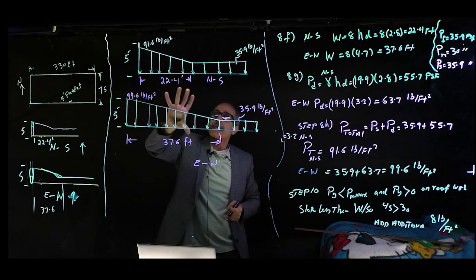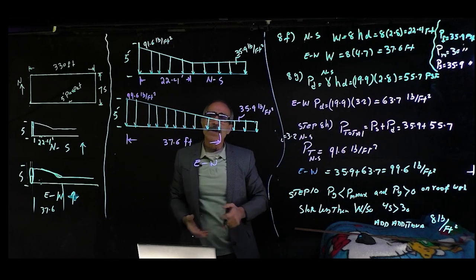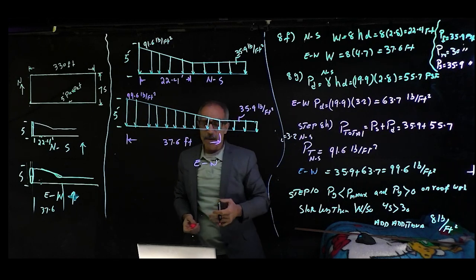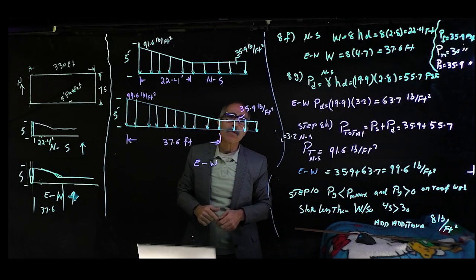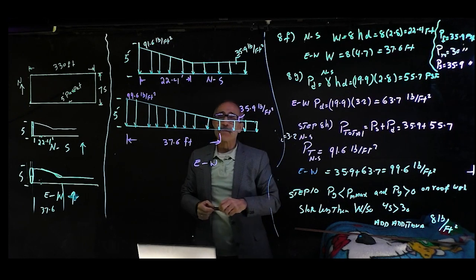This is pound per square foot. So when you do your load calculation, you might have to multiply by the tributary width for a beam or whatever calculation you do. Anyway, don't forget about that. You got an 8 pounds per square foot for the rain.